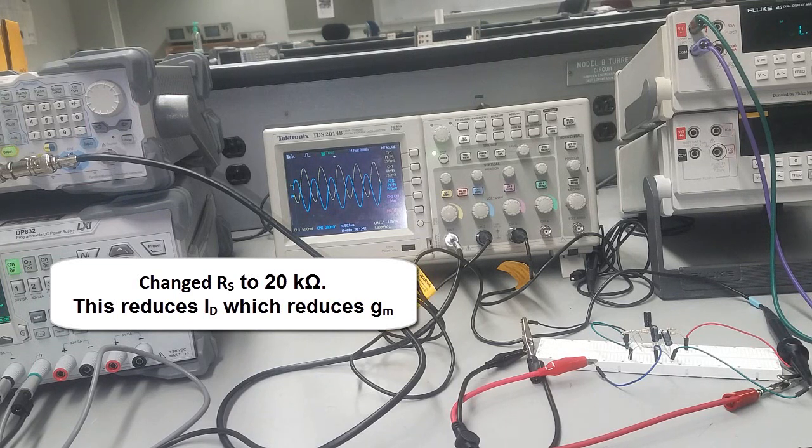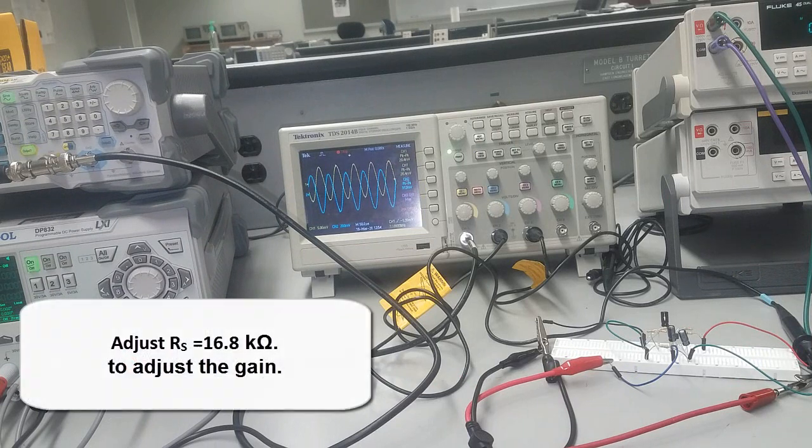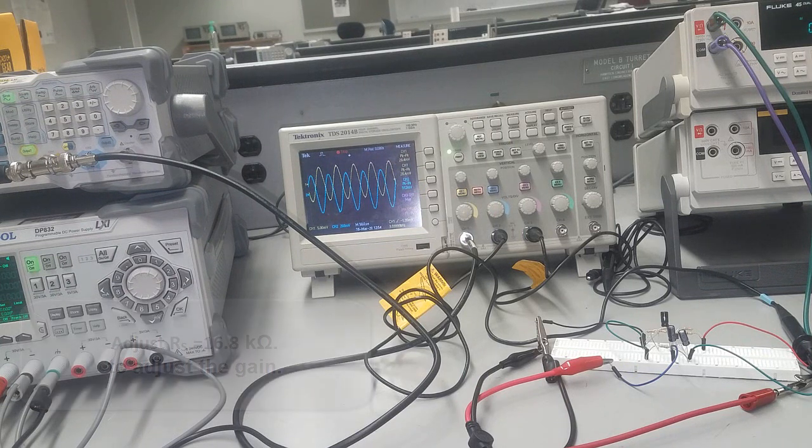But the gain was a little bit lower than we expected. So now we're going to adjust the source resistance to 16.8K. Now with the source resistor at 16.8 kilo ohm, we got a gain within the range specified.